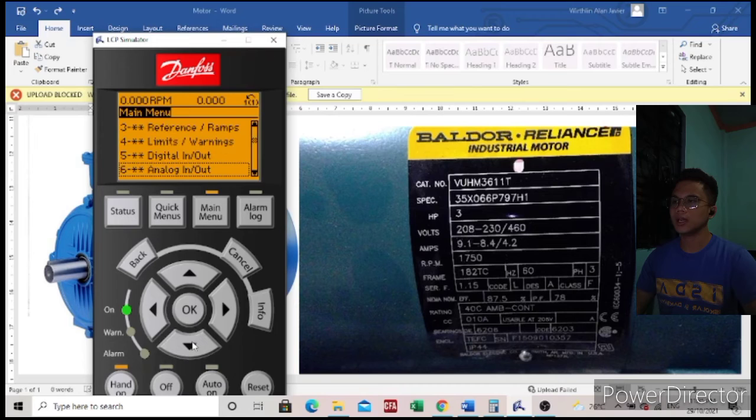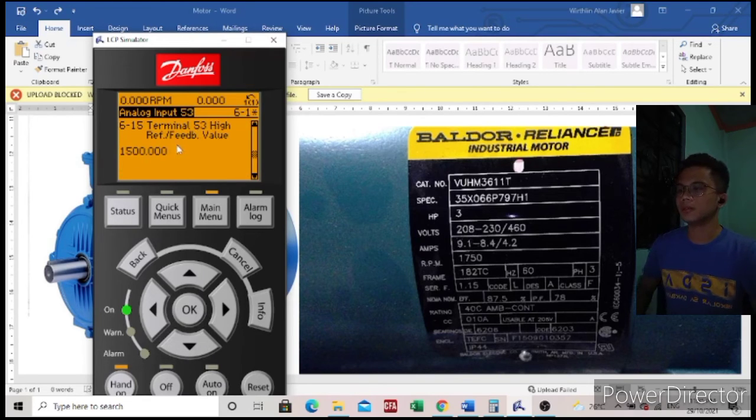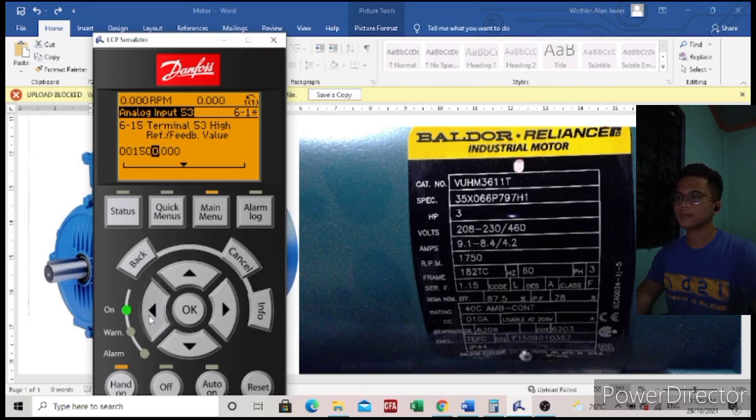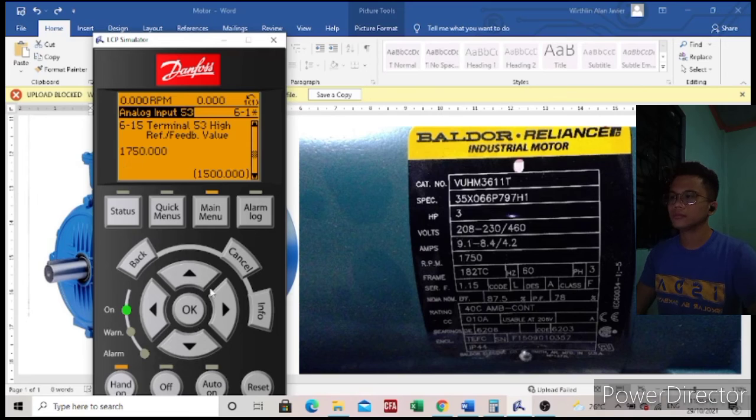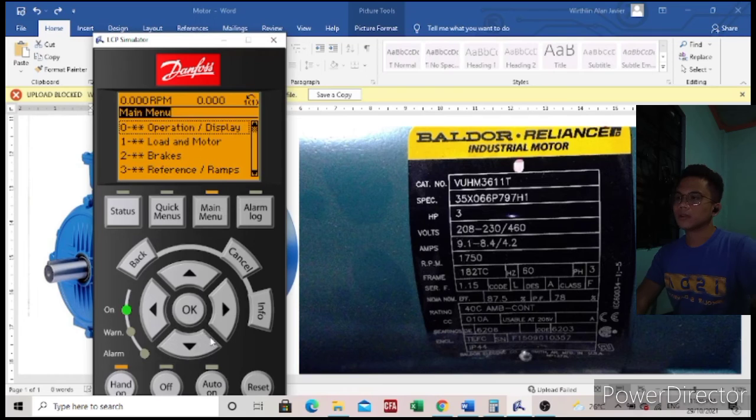Now, next is we need to go to the main menu, go to the analog in and out, analog input 53, skip. Now, for our high reference or feedback value, we need to change this into 1750. Press OK. Next. Okay, since we're done with that, let's go back to the main menu and next.